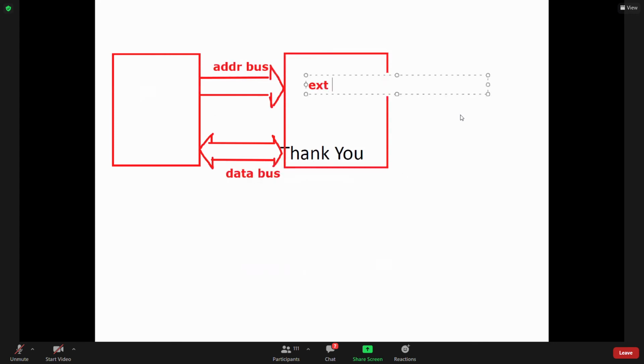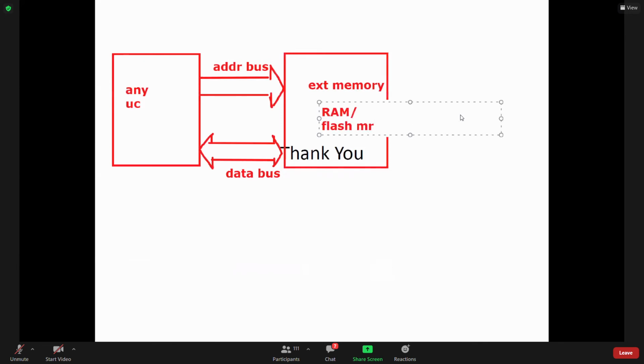This is the external memory, and this is any microcontroller. This doesn't belong to 8051. Take any controller. If you want to interface external memory like RAM or flash memory, then you have to use address bus and data bus. That's it.